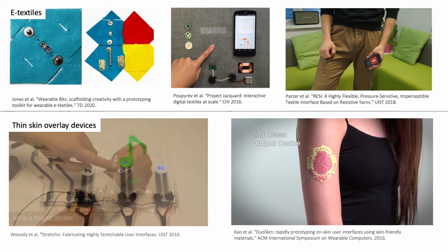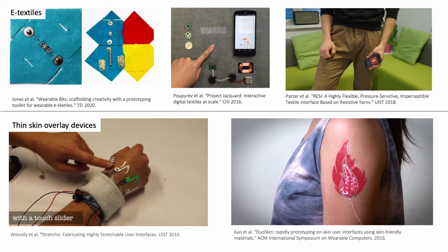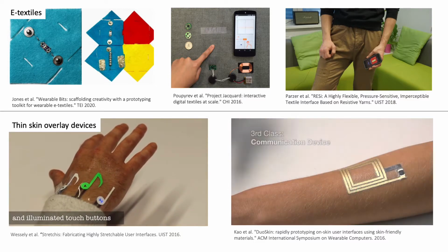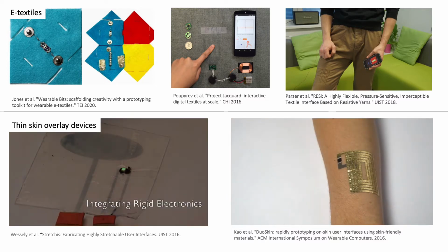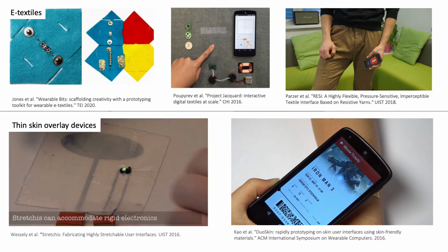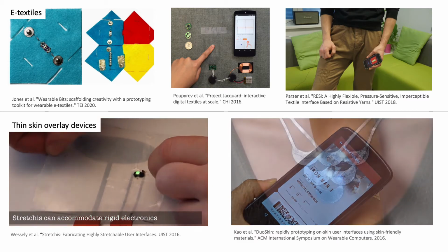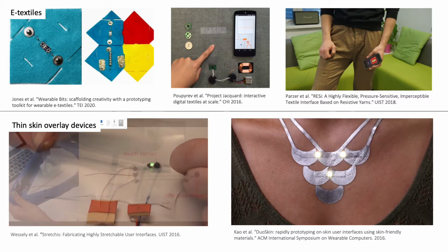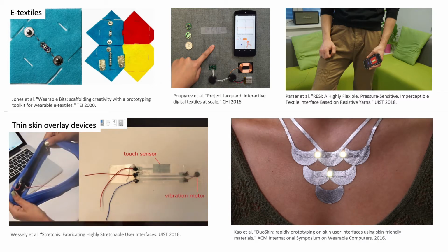Alternatively, we're also starting to see more thin on-body devices for on-skin interaction, as seen by Skintillates and DuoSkin at the bottom of the screen. These prototype thin skin overlays support stretchable wearable devices and can often be considered as interactive skin-on tattoos. The thin skin overlays, such as Skintillates and DuoSkin, can support display output and deformation sensors and sense body posture, depending on controls. But they do require multiple layers of chemical compounds such as PEDOT:PSS for printing and masking for conducting polymers.